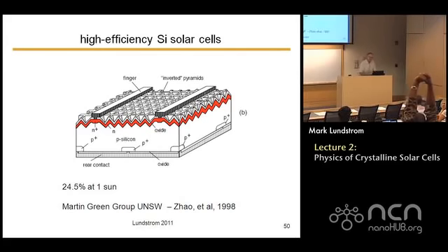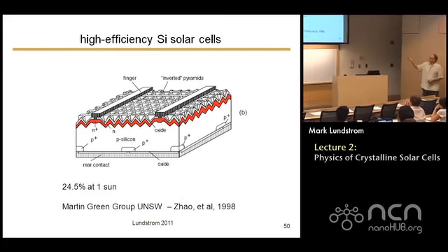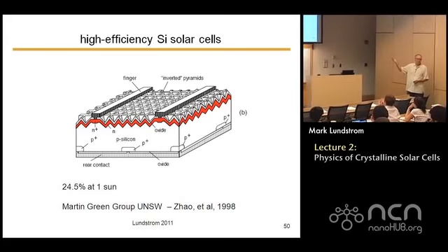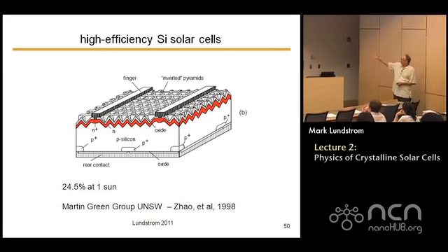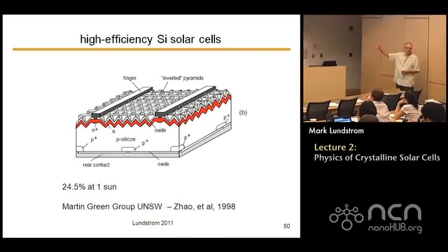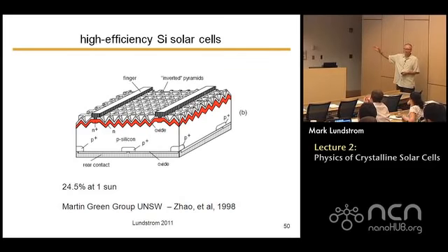So this is one example of optical design where people have spent a lot of care. There are various ways that you can texturize the top surface. They've got a mirror at the back that they've carefully designed to try to maximize reflection. They'll do ray tracing studies to see how many times a ray would bounce around inside this structure. So there is a lot of thought.